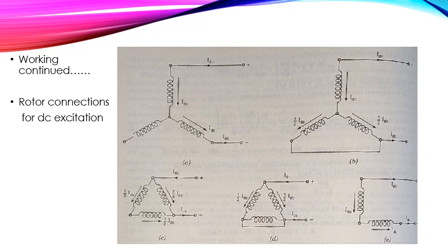It is not so important that the air gap is large, since the power factor can be controlled by variation in DC excitation. Right? Meaning, when the motor is acting as a synchronous motor during normal working condition. So the larger air gap results in a high peak synchronous torque. So the synchronous induction motor is provided with a large air gap, as in a plain synchronous motor. A long air gap gives a stiffer machine with large overload capacity. So there is a direct relationship between overload capacity and air gap.